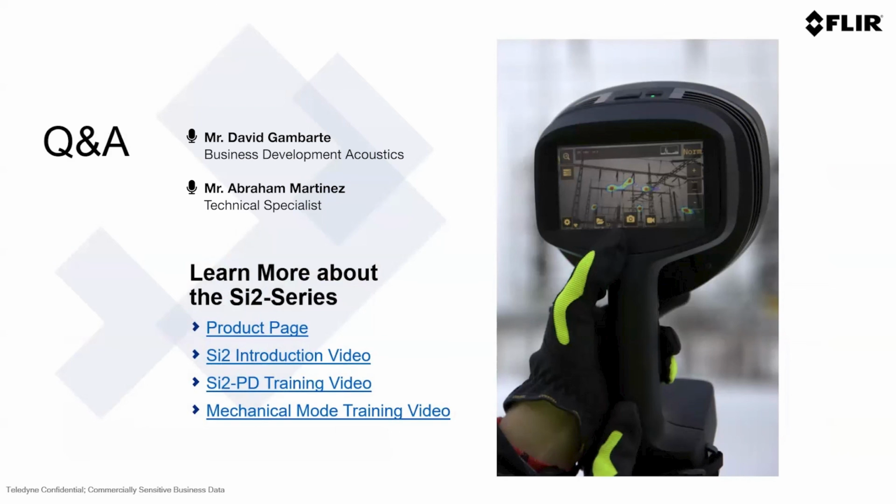Depending on the site where you are, that's where the decision making has to be applied. For example, in overhead lines, we have great expertise, and the camera, the Si2, provides a lot of benefits: the detection distance, the location and detection of the right part of the component where the issue is happening, and it adds a lot of safety for the operations. Those are instant results, and in every case it will vary. As Abraham mentioned, our cameras cannot find partial discharges in underground distribution lines, unless it is a really surface-level underground line. Otherwise the cameras will not be working in those conditions.